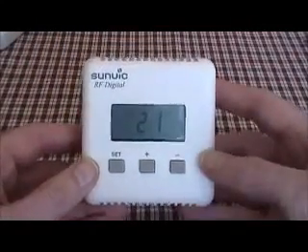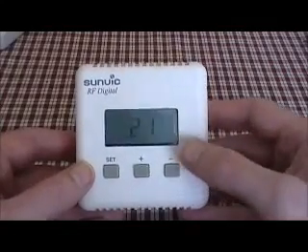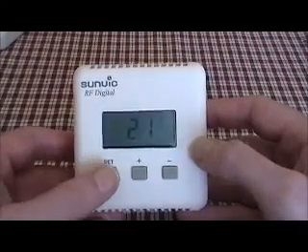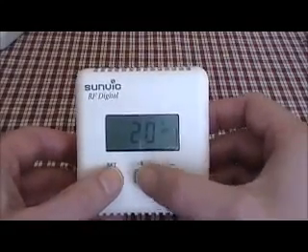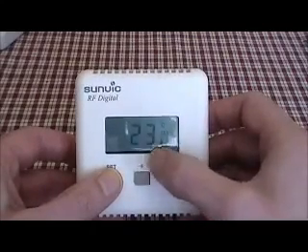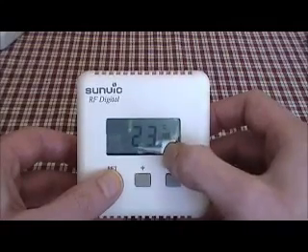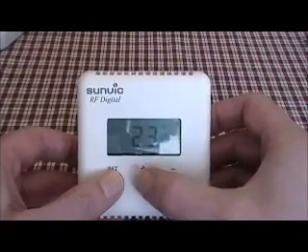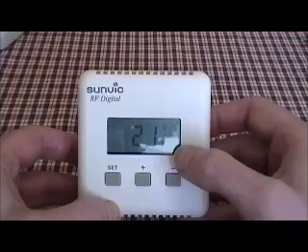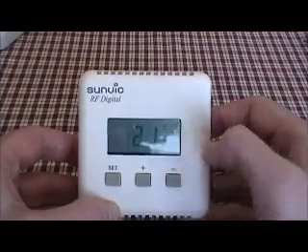This is a digital room thermostat. It isn't programmable. Here we're displaying the actual room temperature, 21 degrees. Press set, and then we can identify the target temperature. So as it moves above the 21 degrees room temperature, you'll see the little gas symbol indicator is lit. Release the set button. It'll go back to the room temperature that it's actually measuring in the room, but will let you know that it's calling for more heat from the boiler.